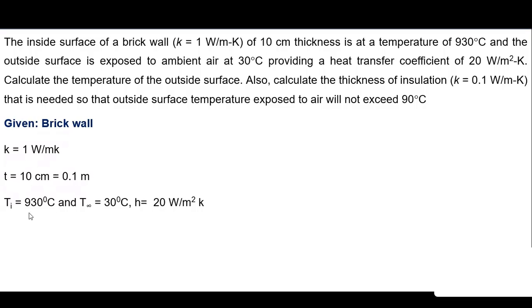Thickness is 0.1 meter, I'm converting it into meters. Inside temperature, I'm calling it Ti, is 930 degrees Celsius. Fluid temperature is 30 degrees Celsius, and h is 20 watt per meter square Kelvin.